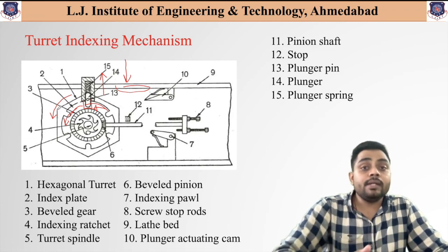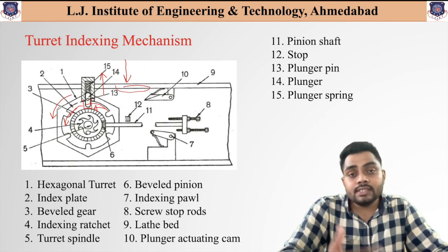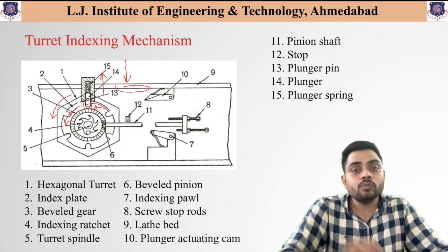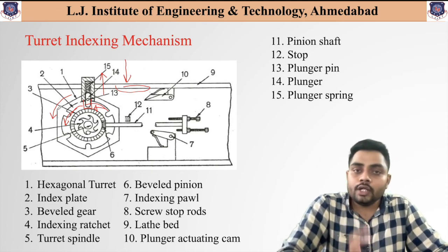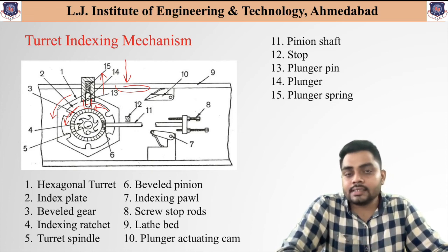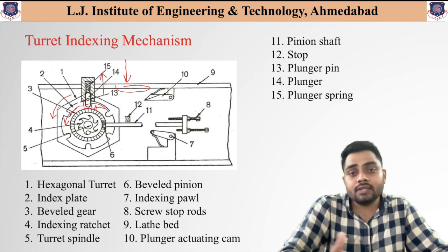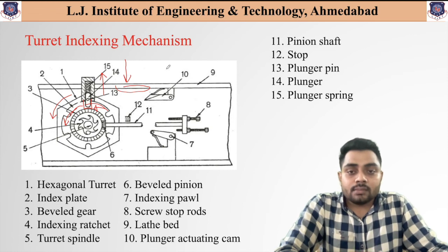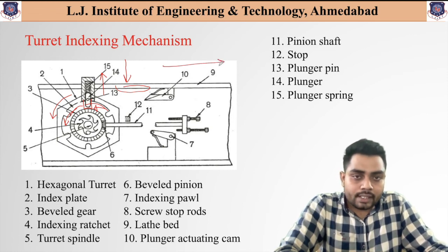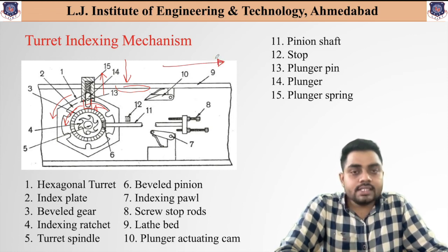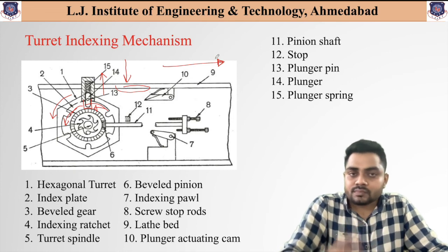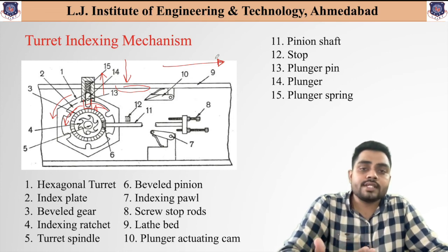According to the requirement of each and every tool, in which particular sequence we need to do the machining, each and every tool is arranged in the turret index head. So based on the machining required, after the machining, when the tool moves back to its origin position, at that time this entire tool changing process occurs.